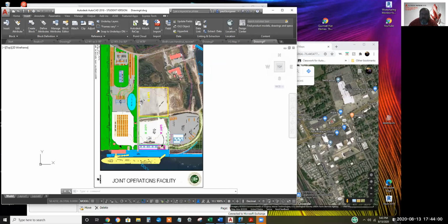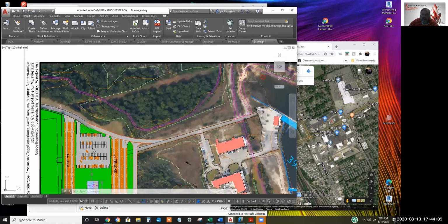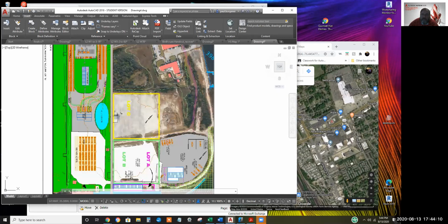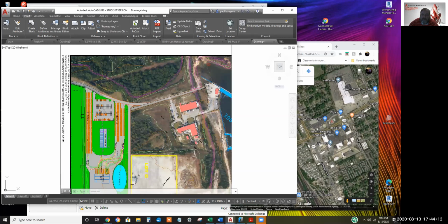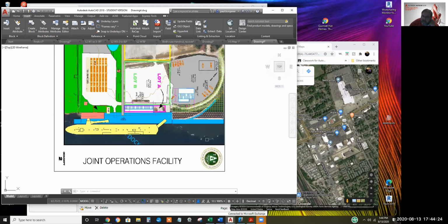This is taking a lot longer than I thought, but anyway, by capturing an image off the internet that has a bar scale somewhere in it, like maps.google, where the bar scale is in the lower right corner, include the bar scale, and with the scale command's reference option, you can enlarge the image so that bar scale is accurate, so that you can click 2 points with the distance command and it'll tell you the number of feet between those 2 points.